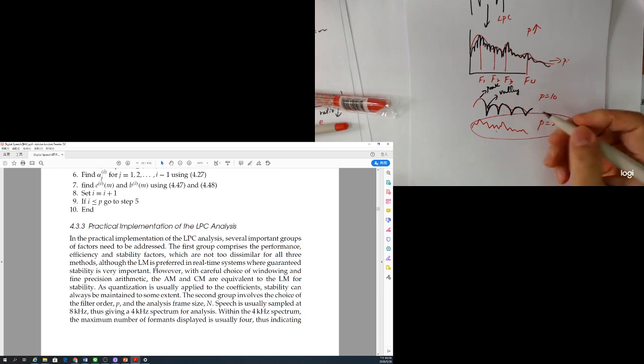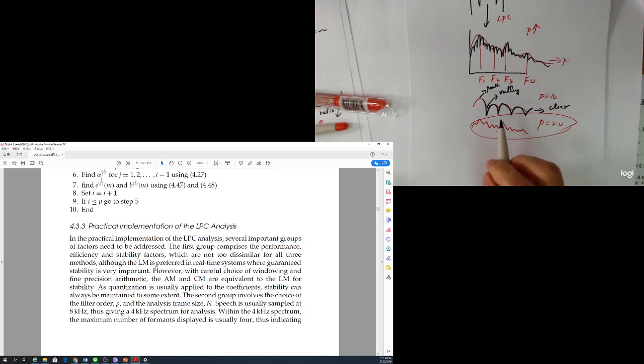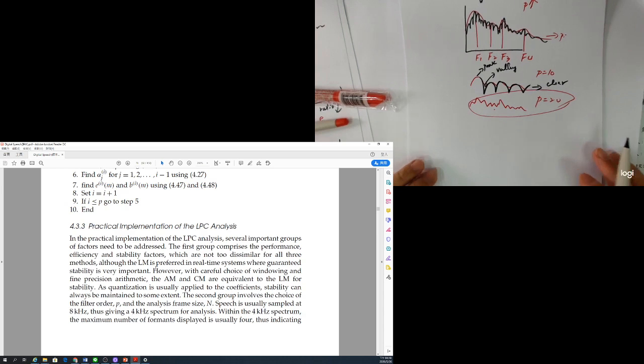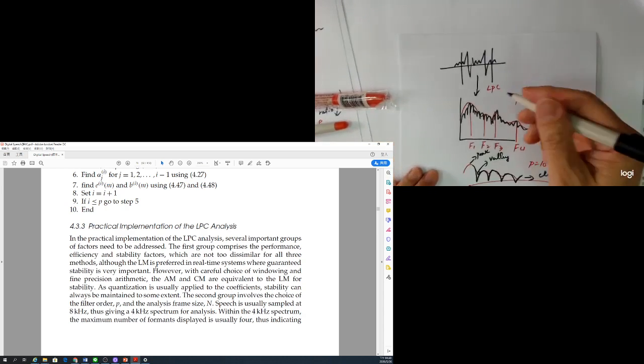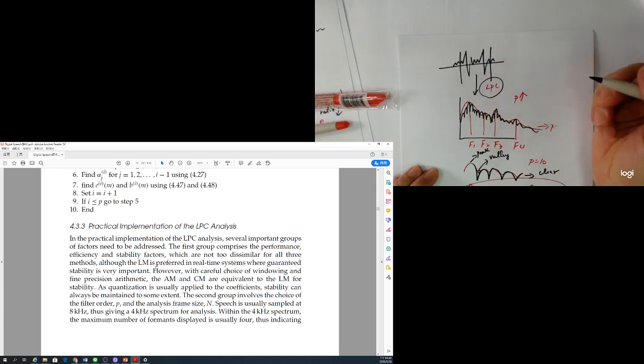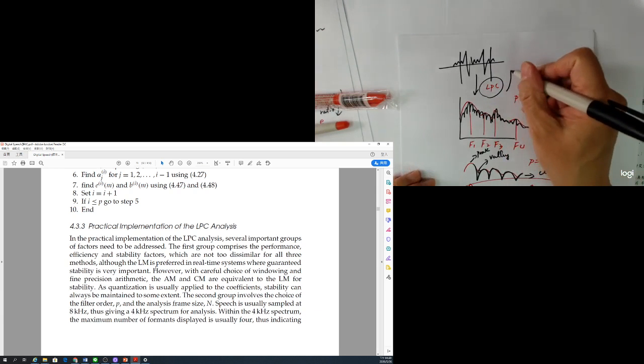And based on post-processing, we can make the speech signal more clear. Because we are an open model, another issue here is that from the original signal we model, we find the LPC signal. So we synthesize it back.